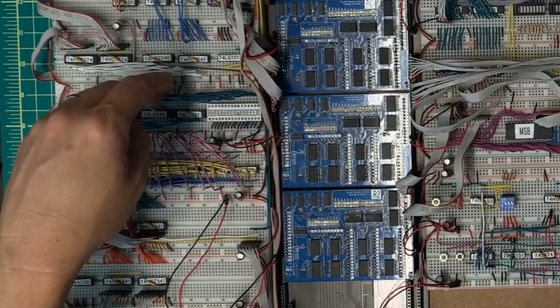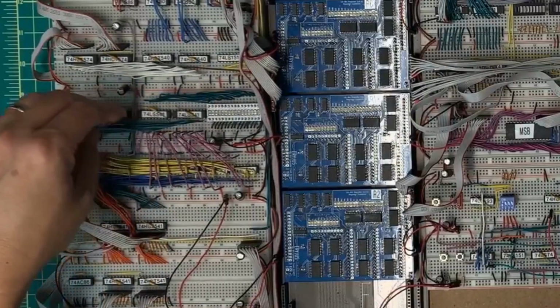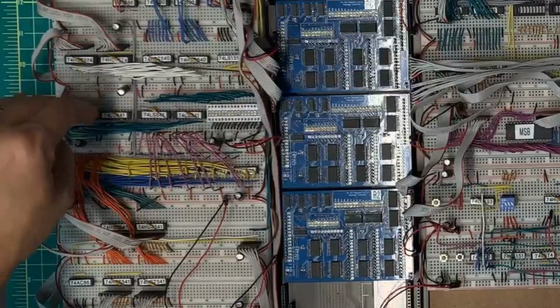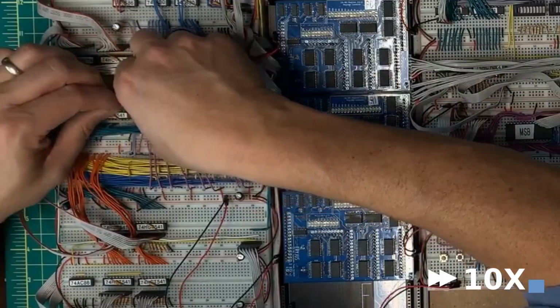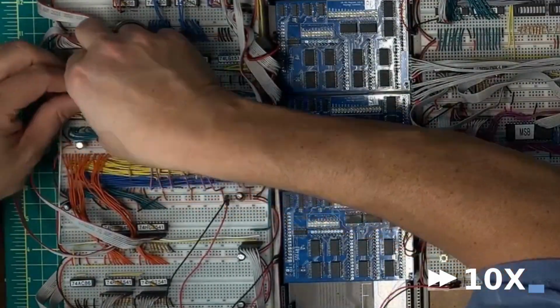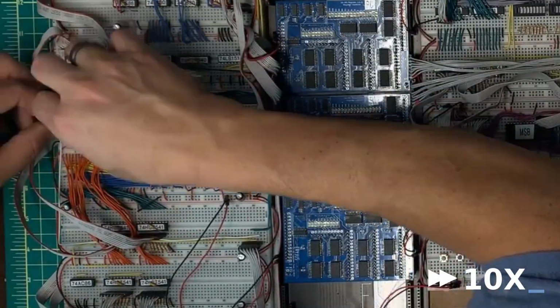The next thing is the inputs into the LEDs are going to be good, but the inputs into the line drivers need to be relocated up here onto the outputs from the ALU bus. I think I said outputs onto the ALU bus. The LEDs need to be driven by what's on the ALU bus, not based on the input from the ALU adder.